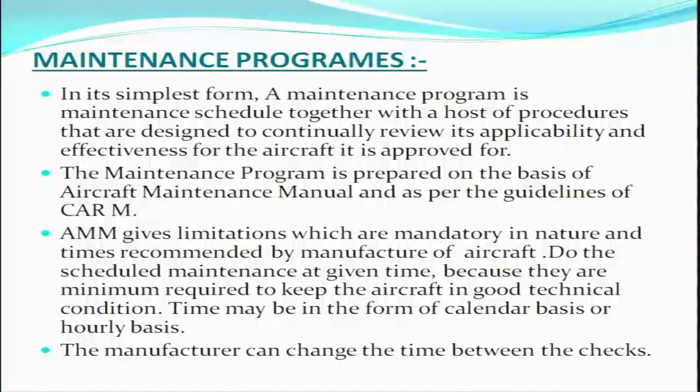Based on the operator's experience, based on the experience of the regulatory authority, certain more instructions may be issued to keep the aircraft in a good condition. The inspection frequencies can be in the form of calendar basis or hourly basis or both, whichever is earlier. And the manufacturer has the full right to vary the time period between the inspections.